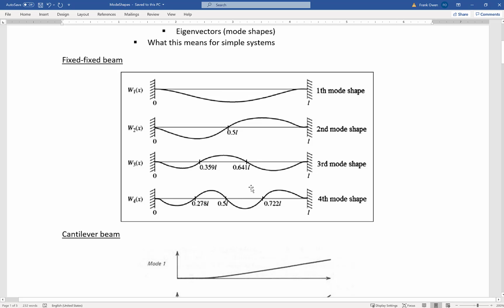But if you excite a structure at one of its modes, even one of the higher order modes, if you excite it at that modal frequency, then that mode shape can become predominant, and we'll see this also. Or it gets to be more important anyway, where you could neglect it if you were away from that modal frequency. If you're forcing the system at that modal frequency, then you may have a problem.